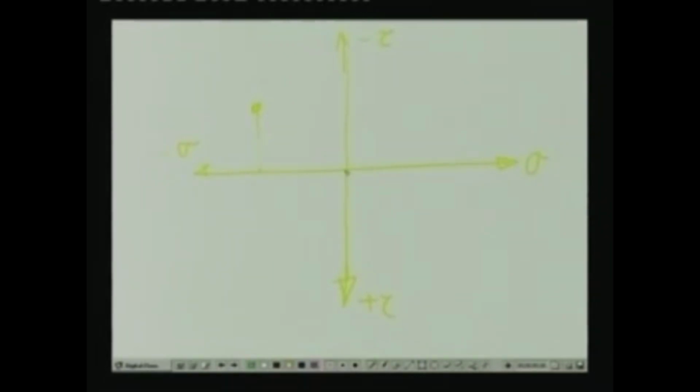Then we have the perpendicular plane, which is the y plane, which is 90 degrees with reference to the physical plane. Here in the Mohr's plane that will be 180 degrees, and we have positive sigma y which is 10 MPa, and positive tau which is 20 MPa. Now, if we join these 2 points, as per our convention, where it crosses the sigma line, we get the center of the Mohr circle. So, with O as the center and OA as the radius, we draw the circle.